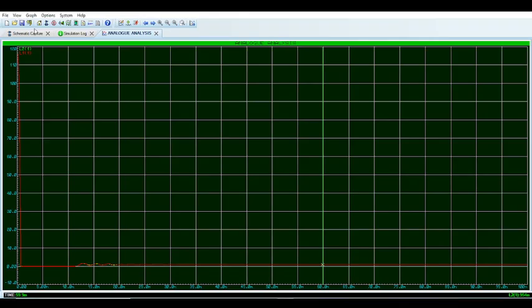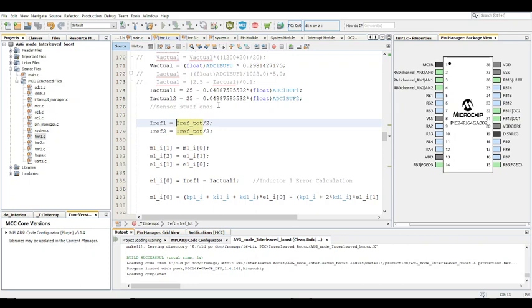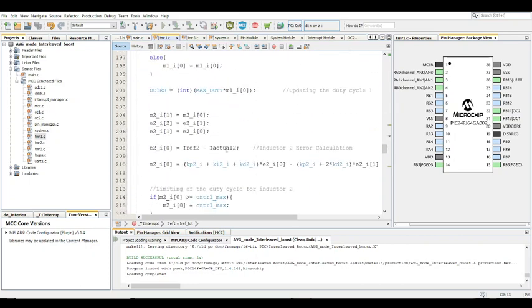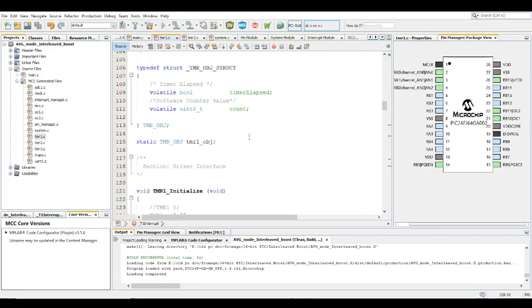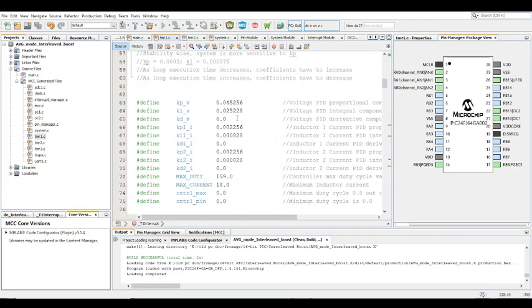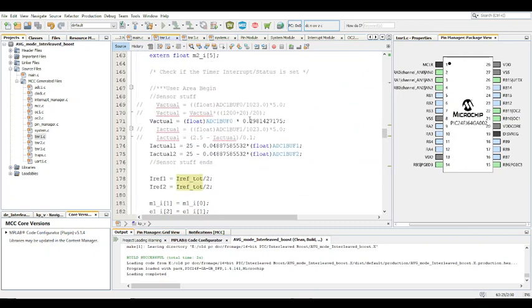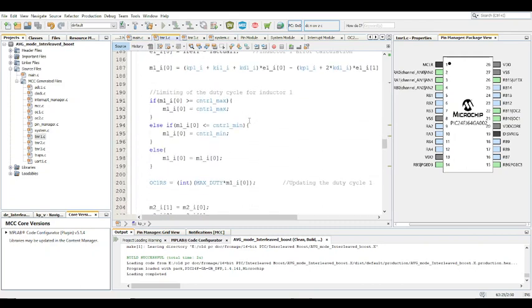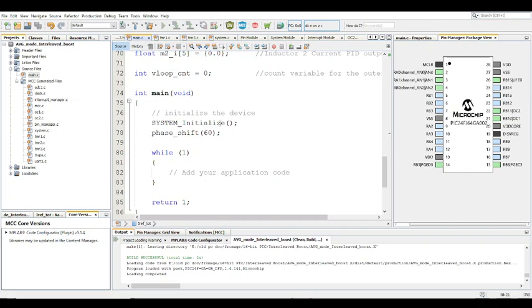Alright, so I can check now and run it again. So it's gonna take some time, I guess. But anyway, you need to check that first and then add the outer loop afterwards with conservative coefficient estimation, KP and KI values, conservative values for those, and ramp it up slowly. So that's that. And yeah, I think that's about it actually. Well, just waiting for the simulation to complete.